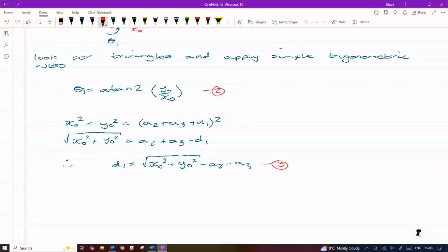Once you come up with a solution, part of the whole control system for the robot could then use the forward kinematic equations I've just seen. You put that as a solution back in, and you check that that position you end up coming up with through the forward kinematic equations is actually allowed within your workspace. So you can use the forward kinematic solution as a bit of feedback to say, is your solution allowed, or is that within a region that's forbidden because there's an obstacle in the way, or are you trying to push the robot through the ground below its fixed concrete base in a factory floor, for example. Okay?